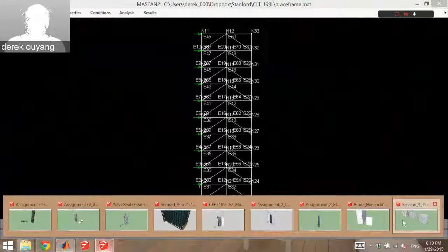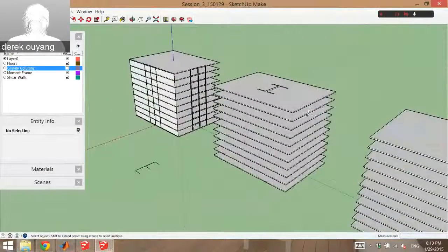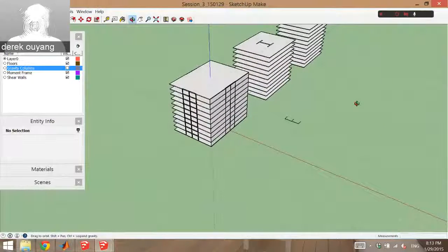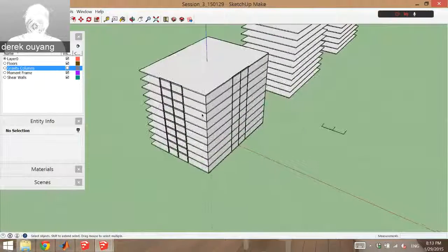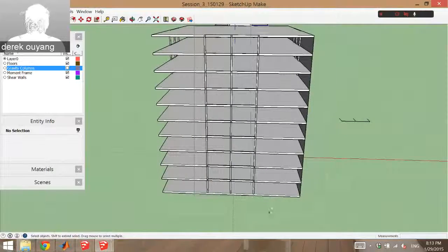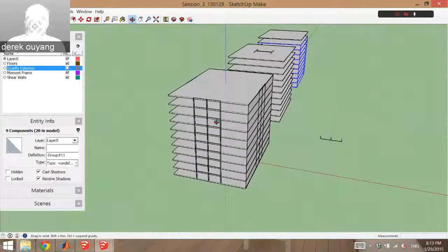Yeah. Go over how you got the tributary area like this. So is the wind coming in the green axis direction on the first tower? Well, it can come in any direction, right? And you're just going to size the worst case scenario, because that's your first reality check. In the grand scheme of things, this is like the first week of what you get from your architects. You're eventually going to size the lateral system in both directions. But as a reality check, you're just going to see what the biggest members are. And so in this case, we're going to focus on this member because it's going to get the most wind force. Basically, the skinny side of your tower is going to be the one you want to start with, right? Yeah, because it's the most area on that.